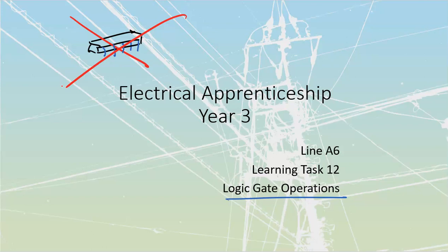But what we're actually going to be doing with this, in a lot of cases, is this thing called function block language. Function block language is a type of language that is utilized inside of programmable logic controllers, PLCs, as we refer to them. Function block is going to utilize everything that we're going to cover inside of here to create outputs for a system.